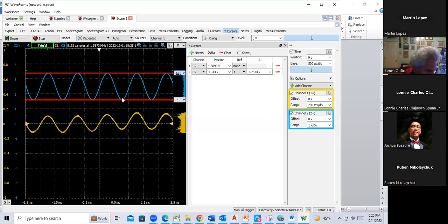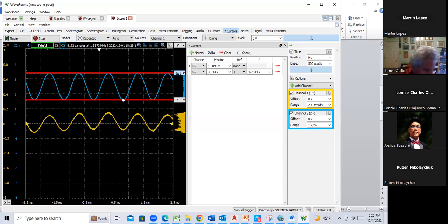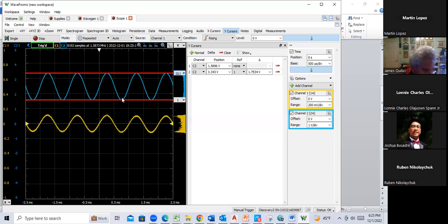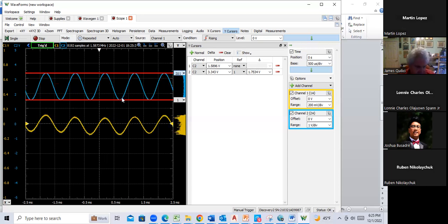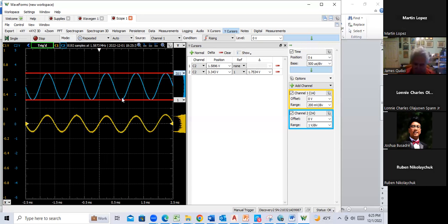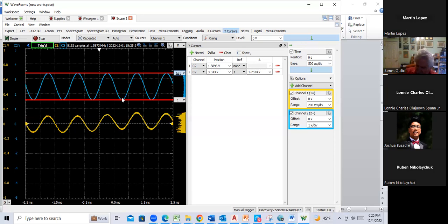Okay. So then step 8 of testing this says check the collector current and bias voltages, and state whether the bias conditions are reasonably close to the design values. So we don't necessarily have to put an ammeter in series. I've got my little handheld voltmeter here. You can use the one in the Analog Discovery too.